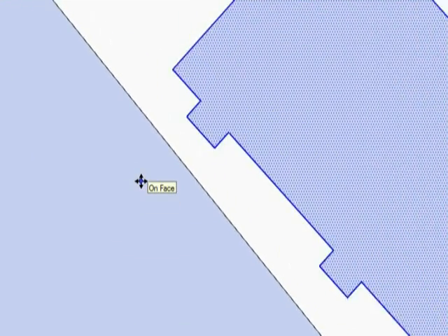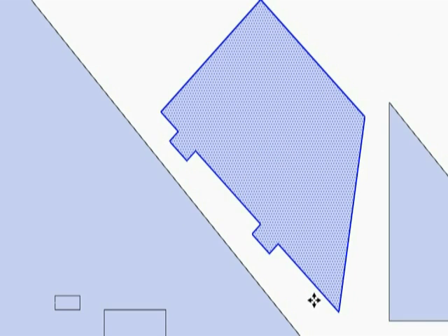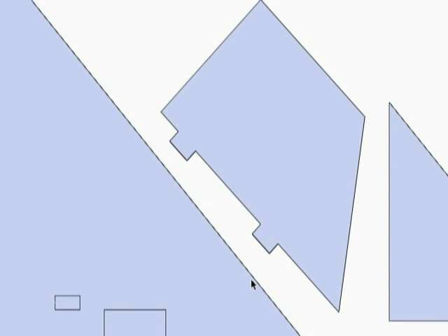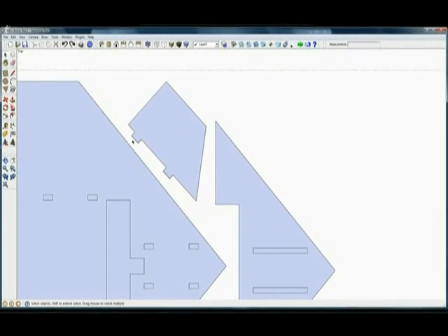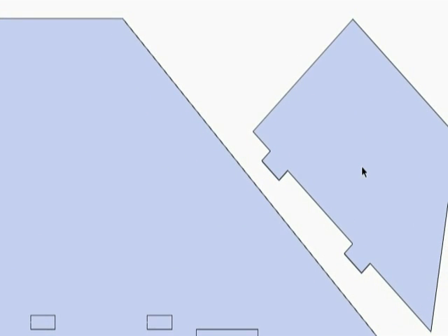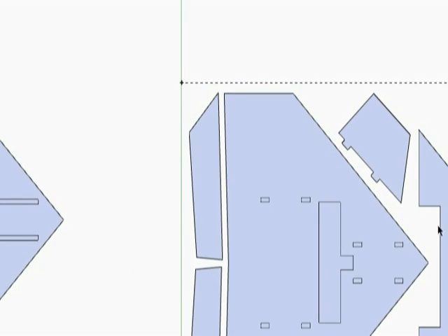So when you're placing your parts, you're nesting them and trying to get them so that you can maximize the use of your foam. Don't get too close. Always try to keep in mind, okay, if I've got a 1/8 inch bit, I should probably make sure that no part is closer than a 1/4 inch. Probably I'd give it about 3/8 of an inch, so that I've got material not touching and the bit's not cutting out of what would be a good part of another part. Enough said.